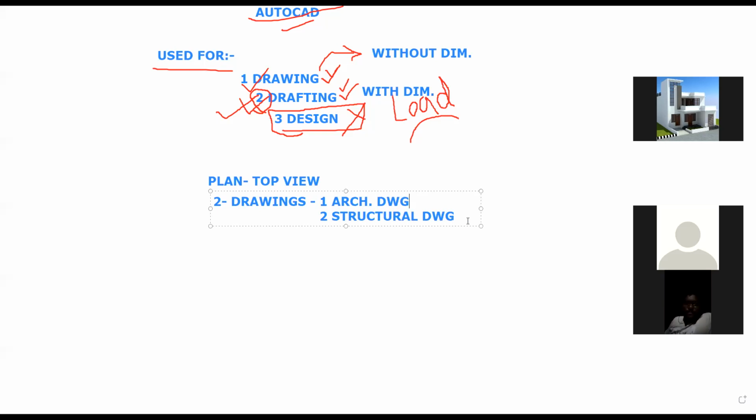Fine. In a structural drawing, you will be giving the details of the structural members such as beams, columns, slabs, footing or foundation, plus the staircase and other structural elements like lift or shear wall design, if required according to the structure. So you have to understand what you are going to produce in AutoCAD. You are actually producing all the details related to site construction. For example, you have to tell the site engineer that you have to show me the clear cover of it. You have to show me the number of reinforcements used.